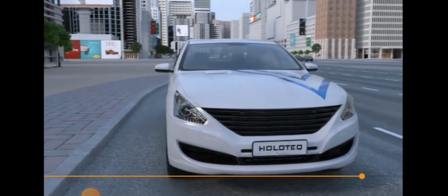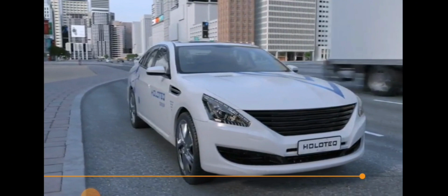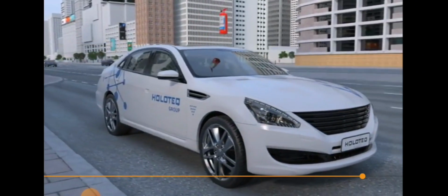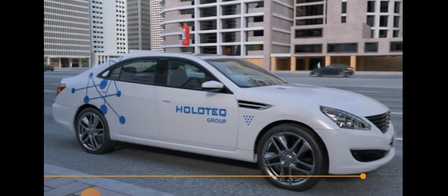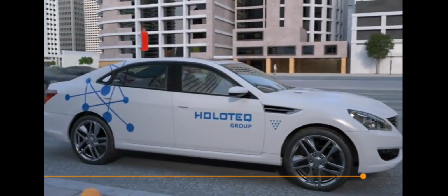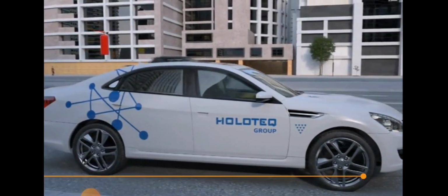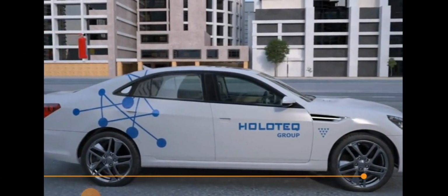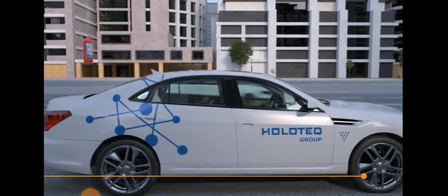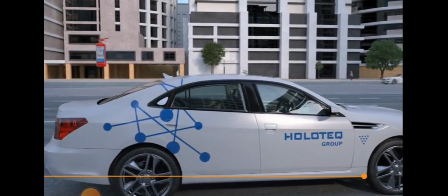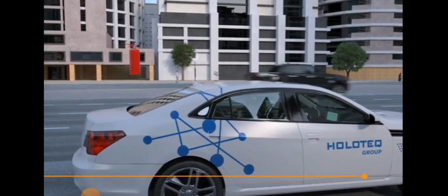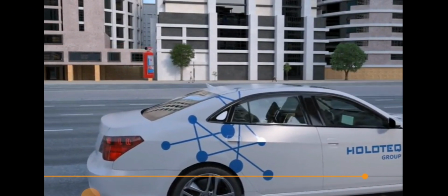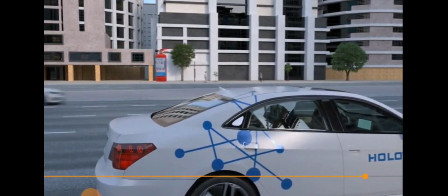Safety equipment in the vehicle. Fire extinguisher. The driver of the vehicle should be acquainted with different types of fire extinguishers in order to choose the appropriate type for the vehicle and load transported. For example, it is dangerous to use fire extinguisher contains water added to soda acid to extinguish fuel burning, as this leads to more spread of fire.